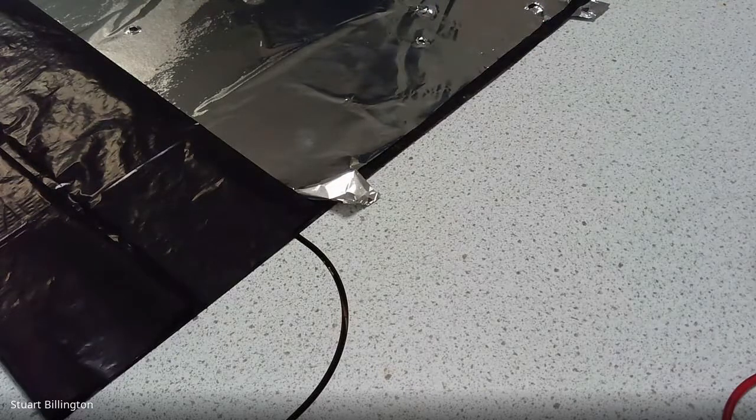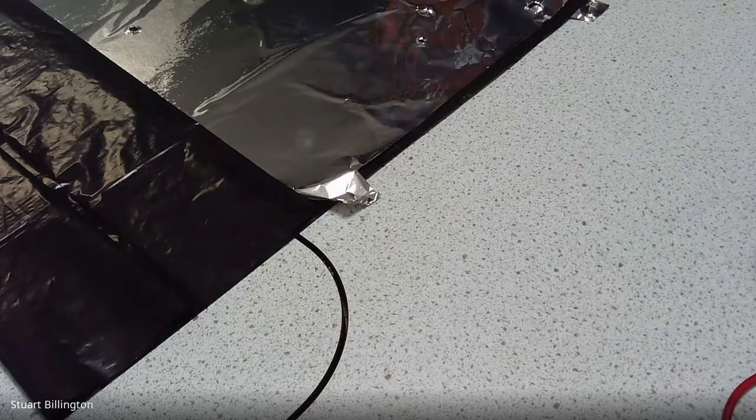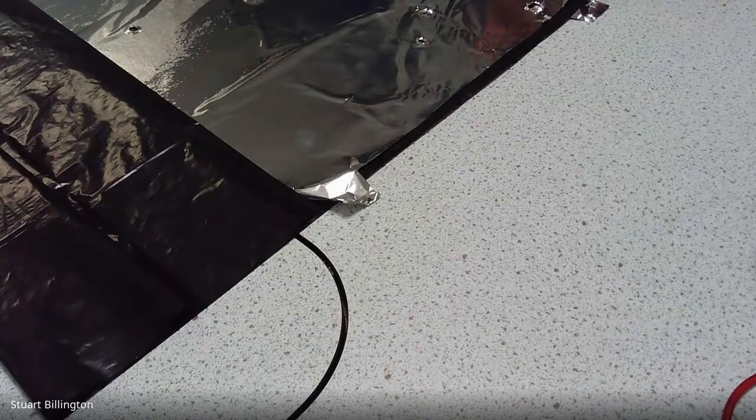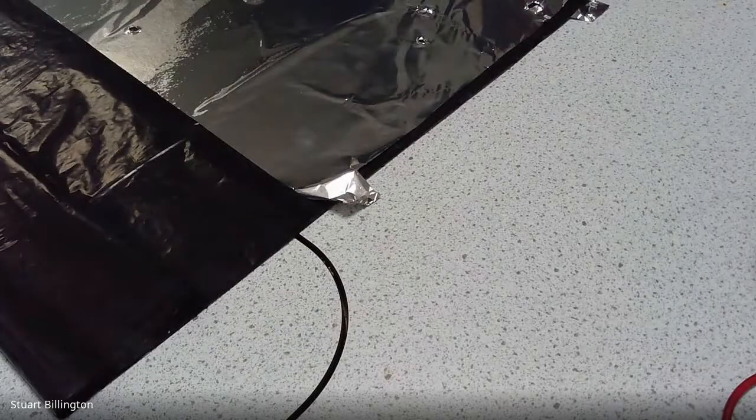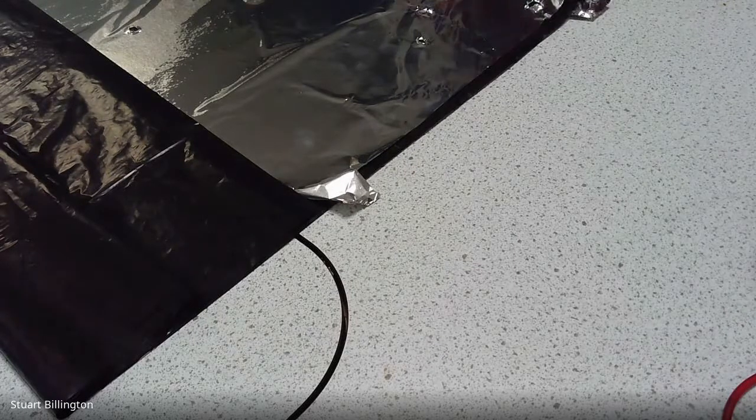And for that reason, we often don't refer to this stuff as an insulator because we might accidentally forget that there's no such thing really as a perfect insulator. Everything is a conductor if you apply a big enough potential difference to it. And so even this bin bag allowed the electrons to conduct when we got up to about 4,500 volts. So we often refer to the insulating material as something called a dielectric. I'll write that on the board in a minute. And that just reminds us that it is going to conduct.